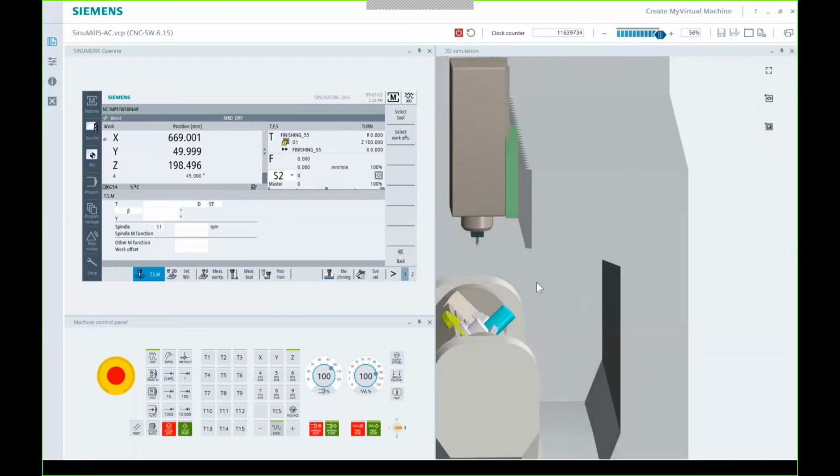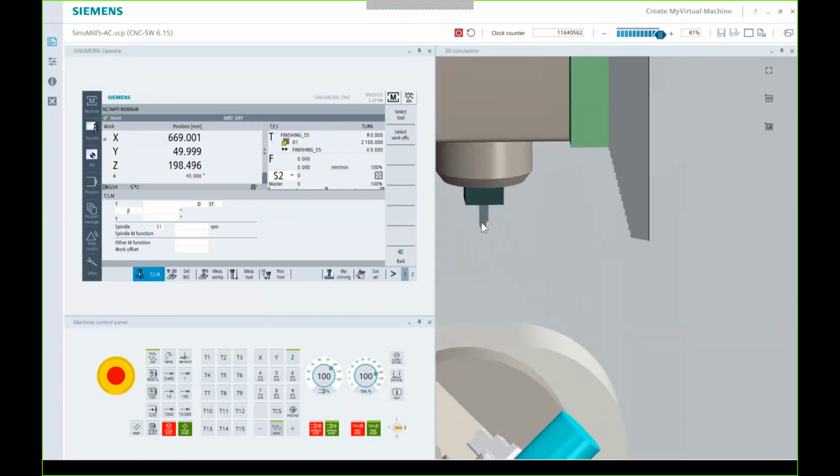So now it's rotated and you can see it oriented the tool as well. But the real nice thing is you can see it put me into the diameter mode. So I have diameter mode on now, whereas prior to that, the diameter mode was not on. And my turning tool carrier, very important, is on.